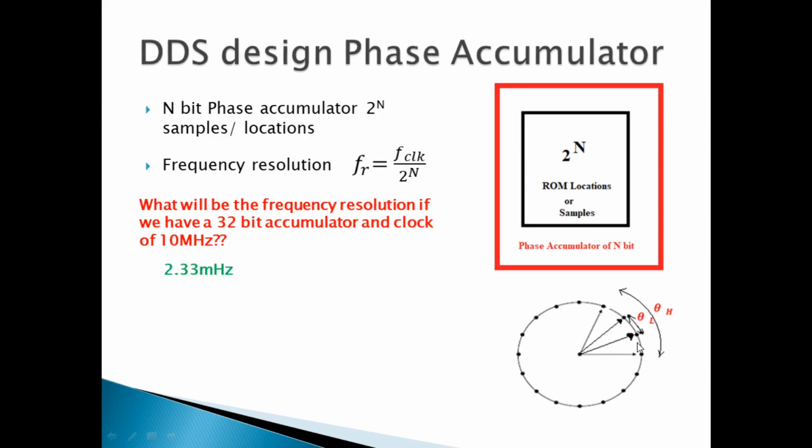So this is the phase resolution which corresponds to frequency resolution. These are points on the phase wheel which represent the phase resolution, theta equal to 2 pi f, and this is the resolution that you would get in this problem.